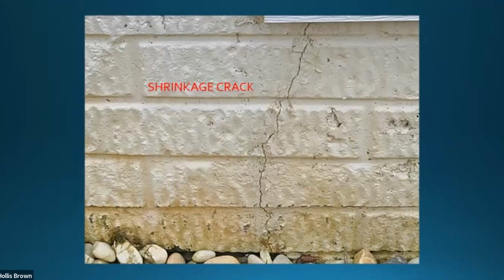If you were to cure a concrete foundation and keep it really wet for 6 or 7 days, you probably wouldn't get any cracks. If you think about all the steel that's in these things and how overbuilt a concrete foundation is for a house, it's pretty rare that it would ever be settlement.